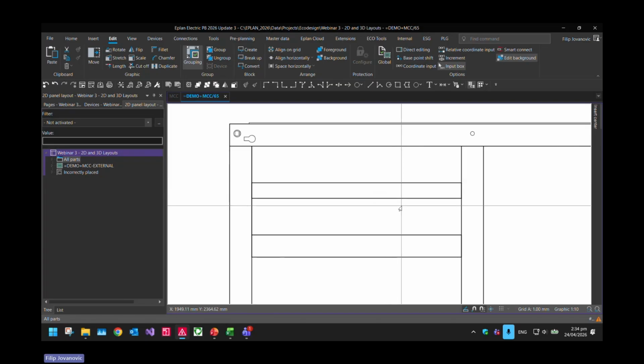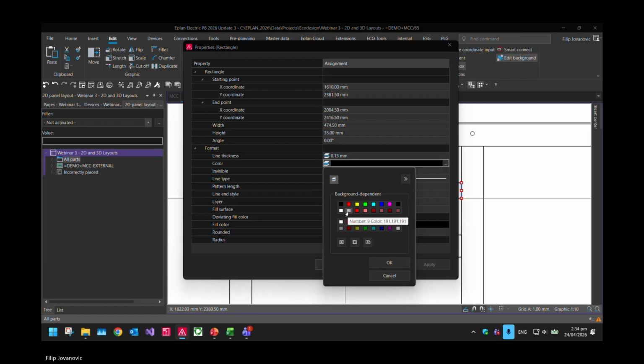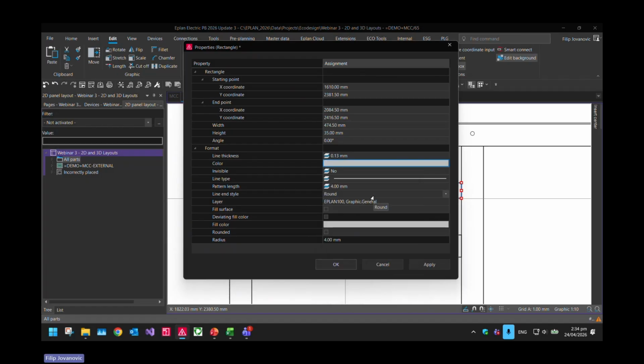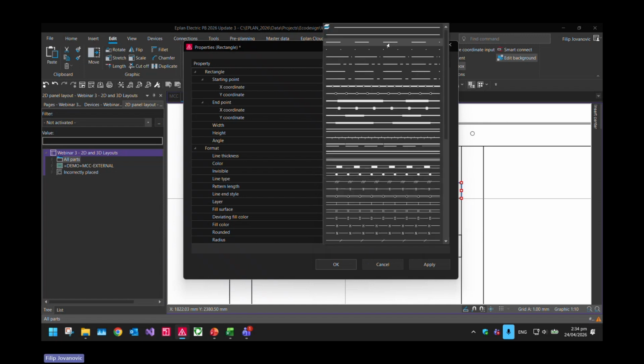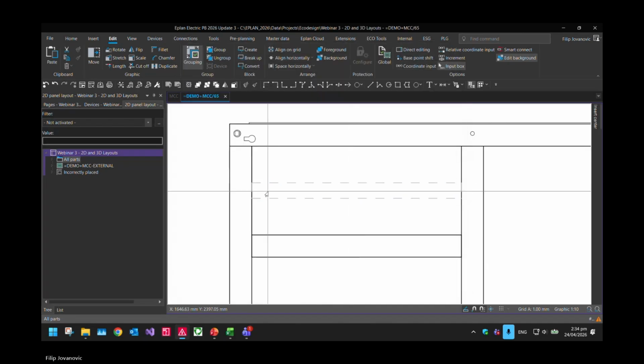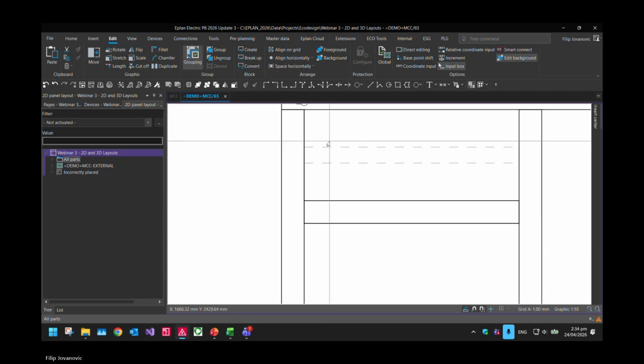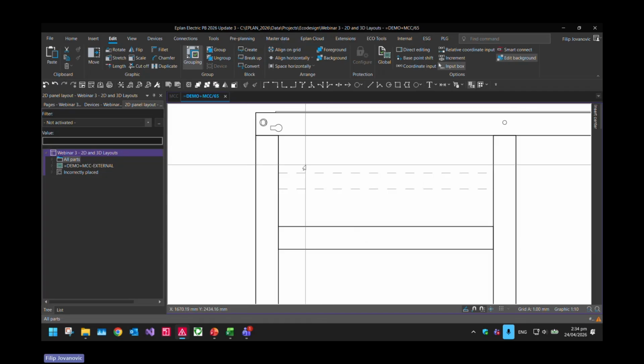However, we're not done because at the moment, this DIN looks virtually identical to the trunking. There's no way to distinguish between them, apart from the height. But we need to do more than that. So we're going to change the formatting. You can make it gray, you can make a watermark. Up to you. I also recommend you make it dashed as well. And then send this to the background. So go over here, background. And this looks much better.